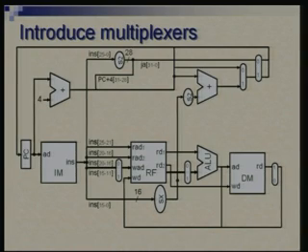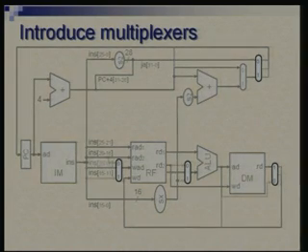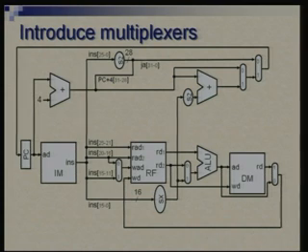It has a provision of passing PC plus 4 as the next address. So, you are either having PC plus 4 plus offset or PC plus 4. So, the provision which we have for PC plus 4 will suffice for non-branch and jump instruction. So, we do not really need a multiplexer there. And let us now remove the conflicting line and put appropriate connections in place of those, and we reach the same design which we had arrived at yesterday.